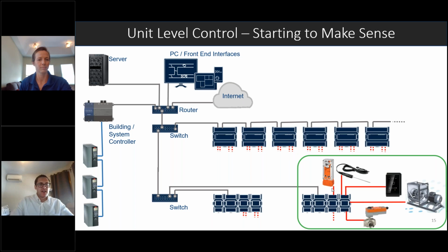Whereas something like, I typically do cost per point and can build it up that way, starting with my electrical and then adding in the controllers and control devices from there. But everyone does have their own method to the madness. So I'd say work with your local controls team to better understand budgets up front on projects. I think it'll save you a lot of headaches on redesigns if you understand where the budget is at with a pretty accurate budget during the design process.